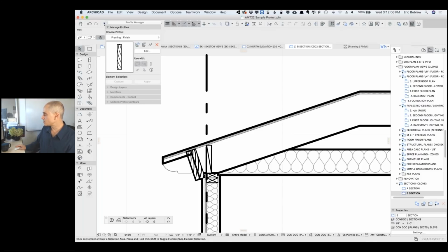He asks about the MasterTemplate international version. Does it include typical UK walls, floors, roof composites, or can we import these from our current template? We did when we created MasterTemplate years ago for international users. We researched UK, Australian, and South African standards, and we put in a whole bunch of different wall, floor, and roof types based on metric measurements. And so you'll find probably most of the stuff you need built in. However, you can easily bring in stuff or just vary it, so yes, that is there.